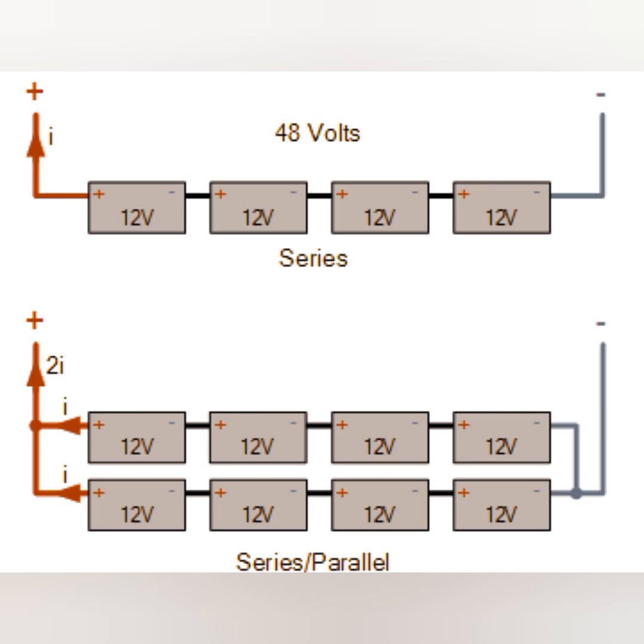So in series connected batteries, the total voltage is equal to the sum of the individual voltages. In the sense, each 12 volt, into 4 batteries we are connected, so into 4, total 48 volt we are getting as an output. Here the current which is taken will be constant or lesser than the rated current level.